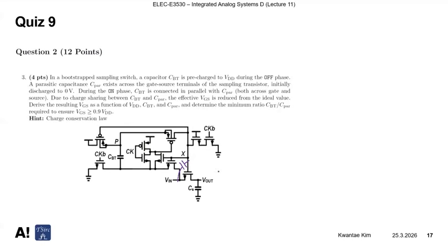And during the off phase, what it means is that Q parasitic is discharged to 0. So this is how it looks, 0 volt. And so let's follow this equation and the situation. To make sure this is turned off, this must be equal to 0 volt. That means we are driving the MOS gate at 0 volt. That means we have to switch off those MOS transistors.